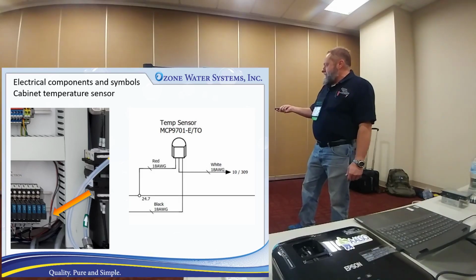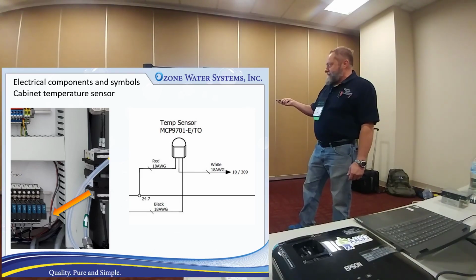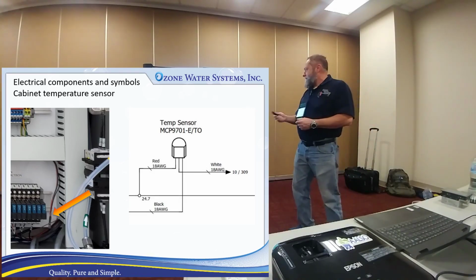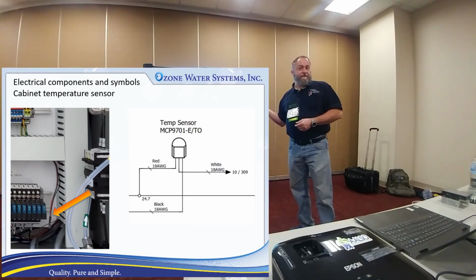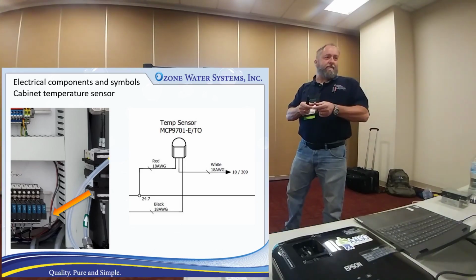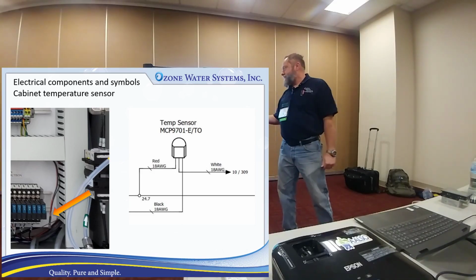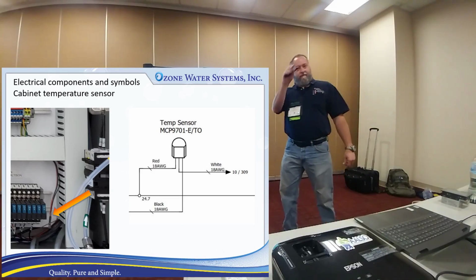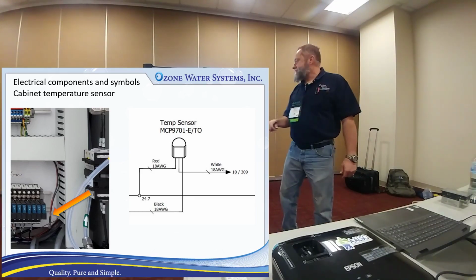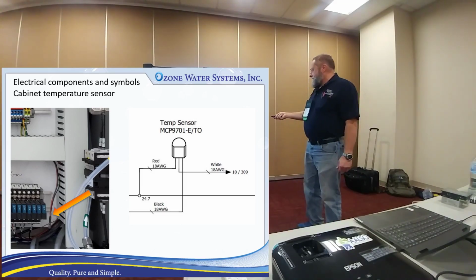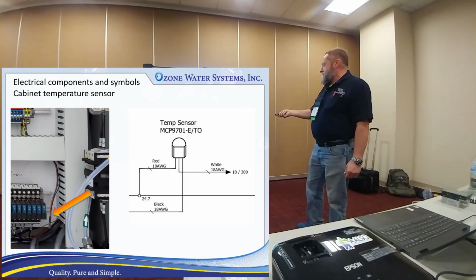What you don't see here, if you follow that wire in on the inside, we just bury it in the panduit somewhere, but this is a 5-volt sensor. So we have a little DC to DC converter in a piece of heat shrink that's just buried in the panduit somewhere that converts 24 volts to 5 volts for that sensor, but it still does go to these same power points. That's your 0 volts, and there's your 24.